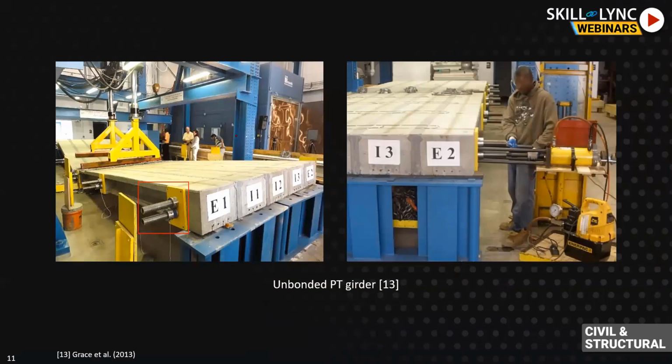You can see that this is a bridge. This is probably a 70 or 80 feet half scale structure. These are the pulled prestressed bonded strands in the longitudinal direction of the bridge, which helps again with the tension on the bottom. But you can also see some in the transverse direction, especially at the end at the bearing locations, where the structure is pulled transversely using these anchor sleeves.